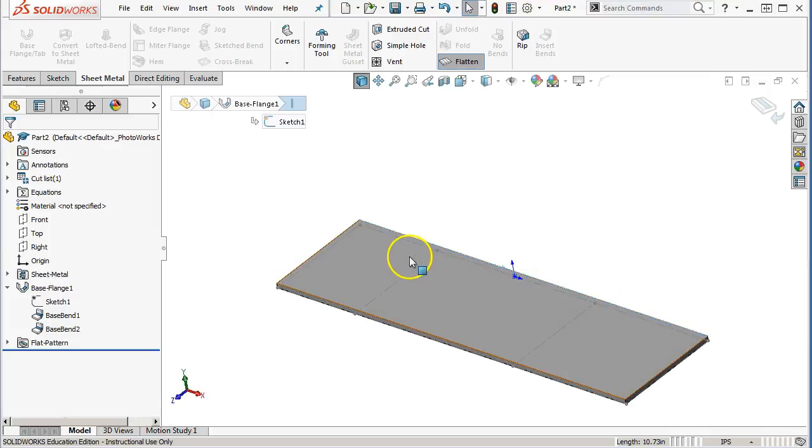That's going through a 60 thousandths bend. That's the deformation in the metal. We know that it happens, it exists. We just don't know to what degree, and how much, based on the material. So that guess of 0.3 is how much this is going to shorten, so that as it deforms going through those bends on this thickness of material, what does it need to be to end up at that finished length? All right, so I didn't take into account the radius. I didn't take into account some of the other possible dimensions that we would need in there. But if I just added up those linear dimensions, I'm quite a bit over.